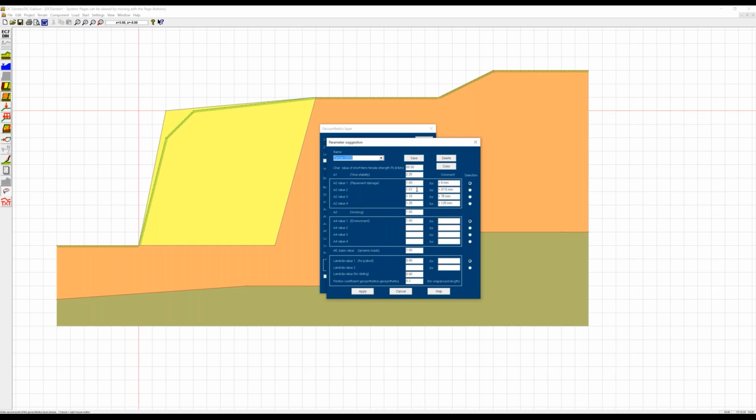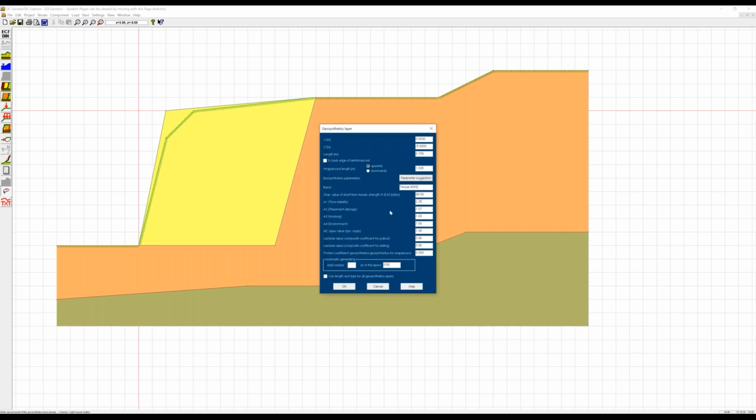And we can select which value here to use. So these reduction factors are transferred to the dialog, and you will see later that the characteristic strength of 88 kilonewton per meter is reduced by the different reduction factors here and by the safety factor for the stability of the total construction.